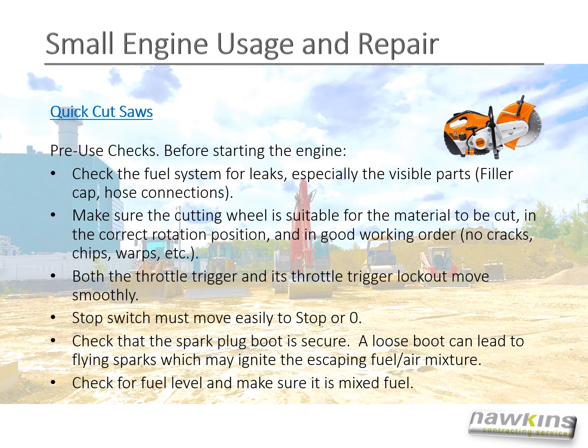Check that the spark plug boot is secure. A loose boot can lead to flying sparks which may ignite the escaping fuel-air mixture. Check for fuel level and make sure it is mixed fuel.